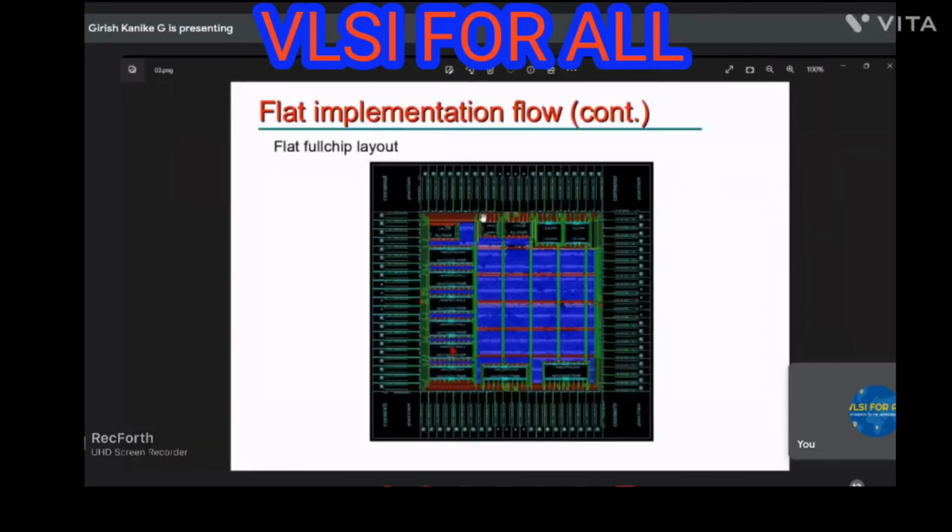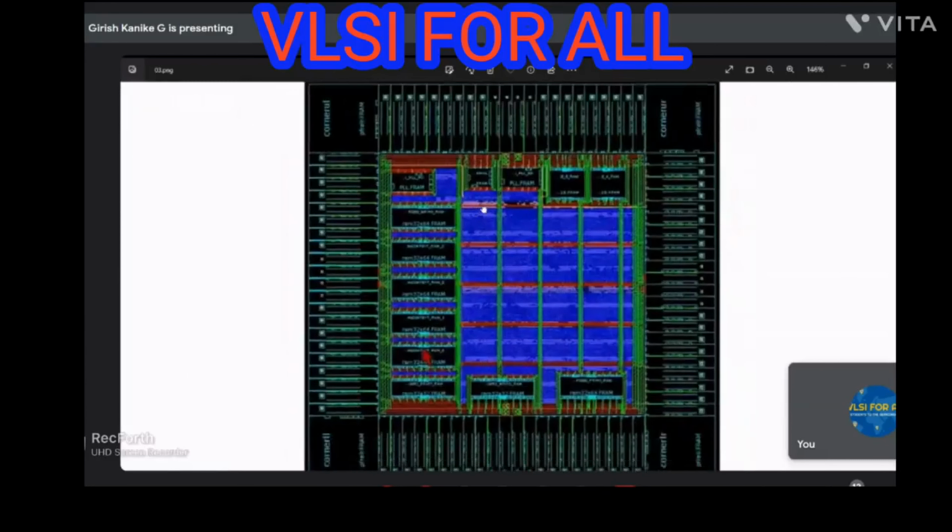This is on the metal layers, because you don't design a full chip on a single area; it is divided into layers. For example, I worked on a chip where the design had 7 metal layers. The basic layer was the pins and all. The first metal layer was standard cells. The second was the power for standard cells. The third and fourth were for some pins and again some macros.